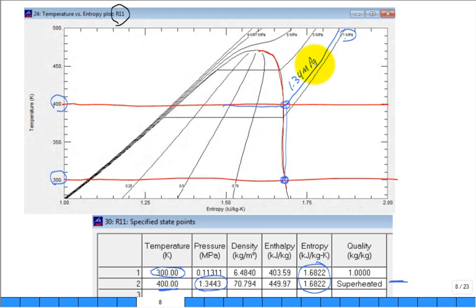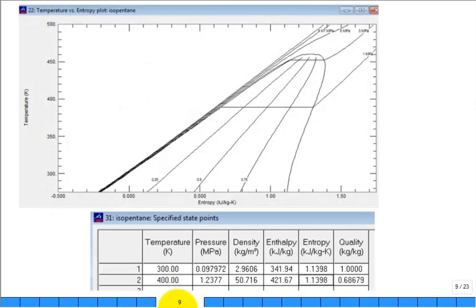It's actually because a lot of that heat is being brought in close to the high temperature source from our Carnot studies. That's great for performance, isn't it? Not a whole lot of superheating. I mean, a lot of the heat's brought in there. You could work with the cycle down here to improve efficiencies with feed water heaters and reheat, but let's leave that alone. You can even go and find a fluid, isopentane. Take a look at that slope.